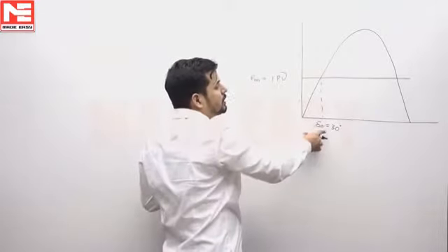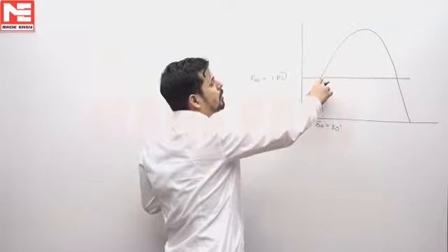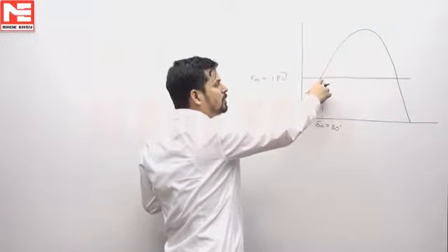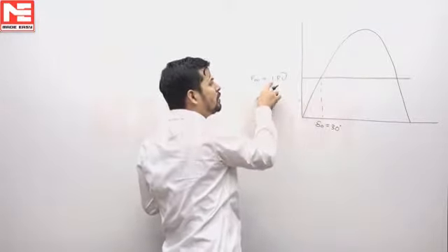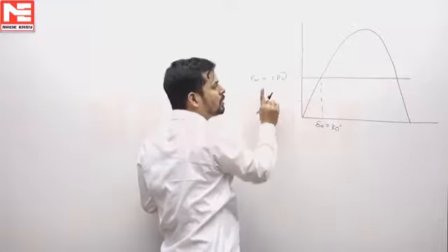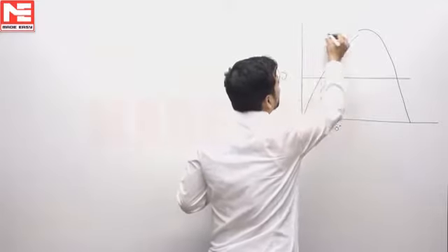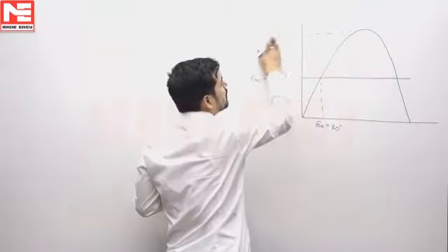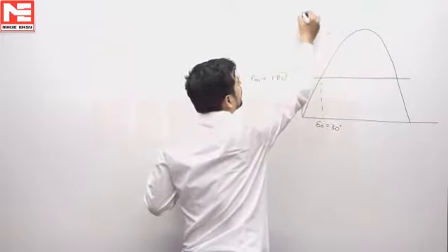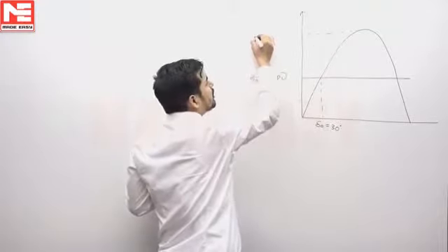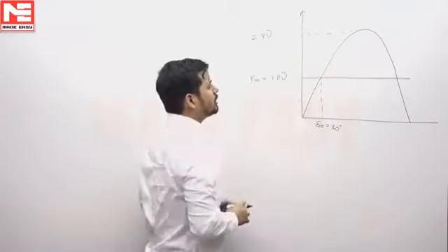We know that at this 30 degree, the electrical power output of the generator is equal to the prime mover input of the generator, equal to 1 per unit. Using this logic, we can say that the maximum power, the PEM value in pre-fault condition, will be 2 per unit.